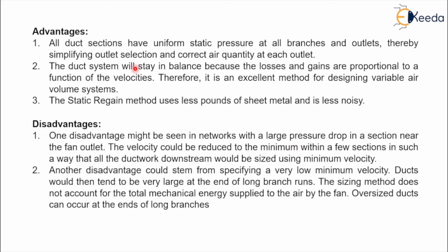The duct system will stay in balance because the losses and gains are proportional to a function of the velocity. Therefore, it is an excellent method for designing variable air volume systems. The static regain method uses less sheet metal and is less noisy, because there is a reduction in the velocity, or what we call dynamic pressure loss.